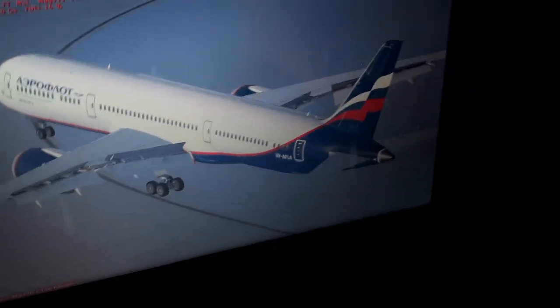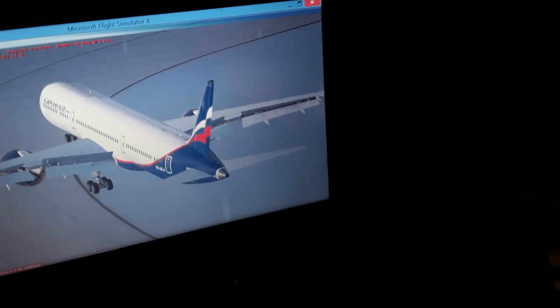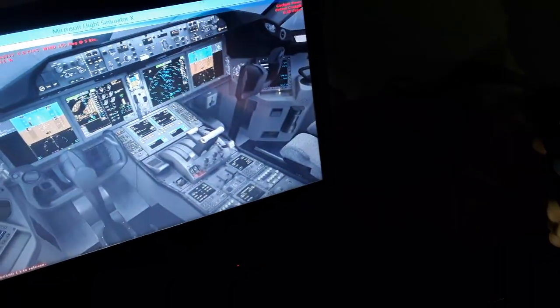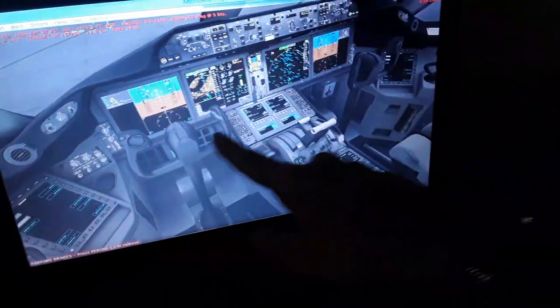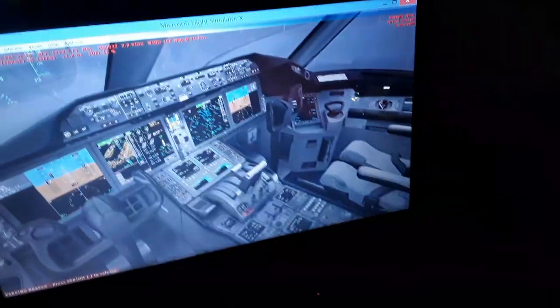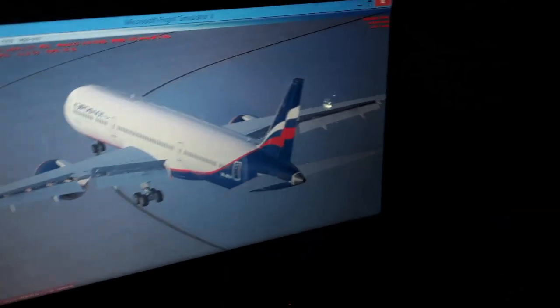It's locked to zero position automatically from the computers. So we have only the rudder for steering the aircraft on the runway for takeoff above 144 kilometers an hour, or 80 nautical miles per hour. So we have the rudder pedals again for that. You can see the rudder pedals also have the toe brakes over here you can press, and we also have the nose wheel steering tiller for slow speed nose wheel steering over here.